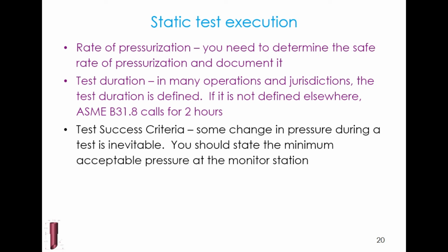monitor station. Some people allow the introduction of more test fluid to make up for temperature change, and I don't do that. I find that way too imprecise. I don't know if what I added was a little bit of water or a lot of water. So basically what I say is the operator can drain fluid out if pressure is increasing, but they can't add fluid if pressure is decreasing. So when I say that, I have to say, how low can it go before the test fails?